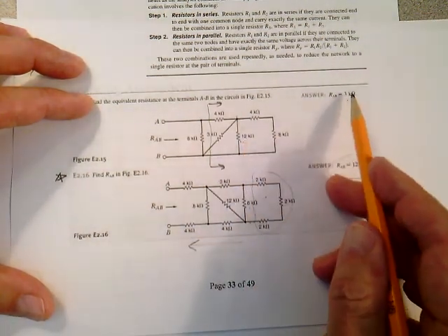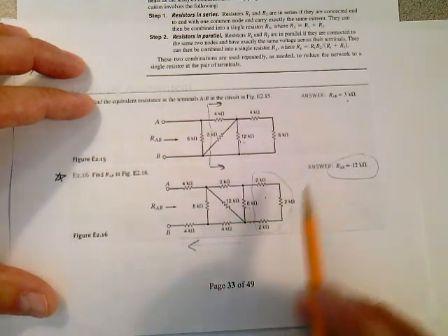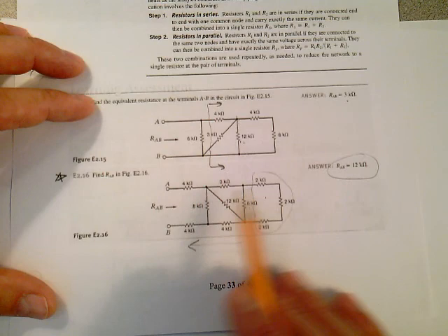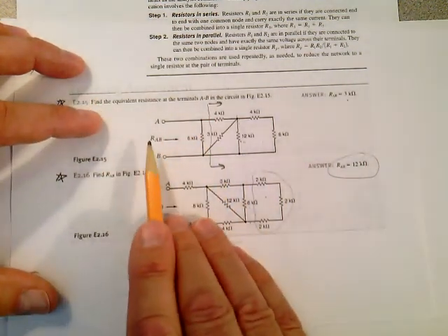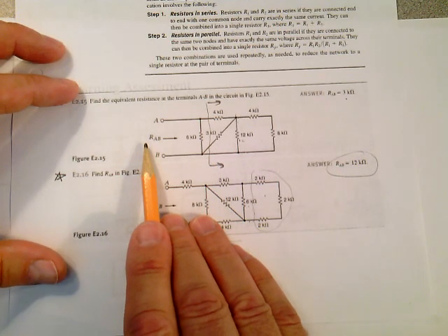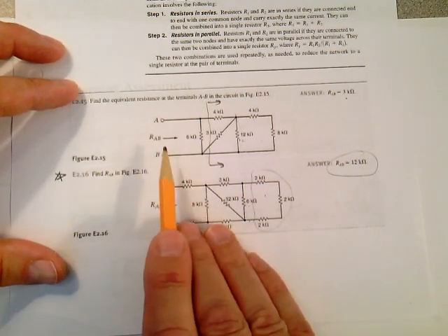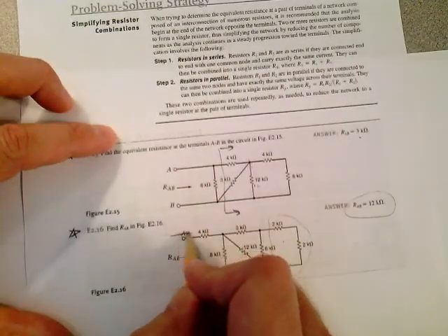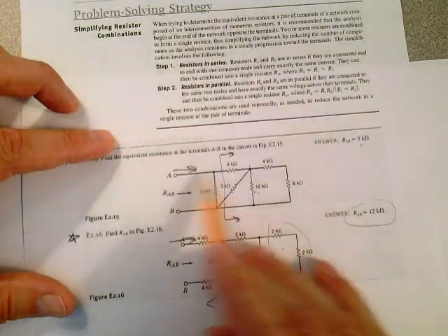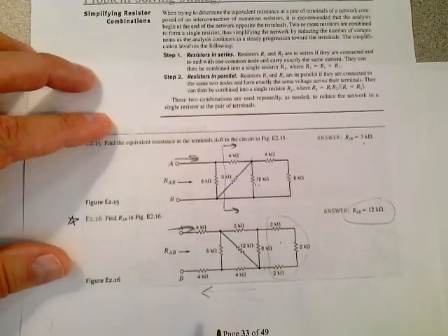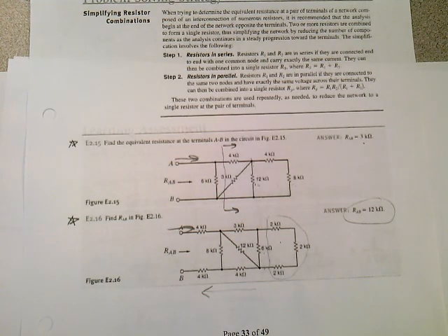Up here, you get the 3K looking in from the left. And why are we trying to find these total resistances in these circuits? Because once we know the total voltage, we can divide by the total resistance and get the current flow here, getting the total current coming in there, or the total current coming in there. And then we can find these different branch currents. That's the next lecture. That concludes this lecture.